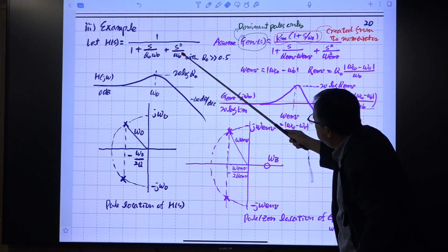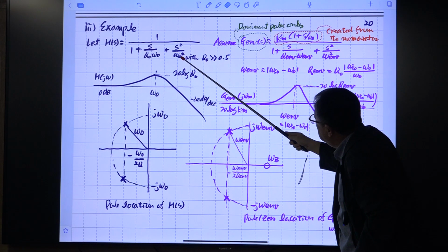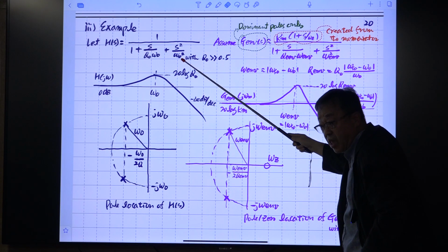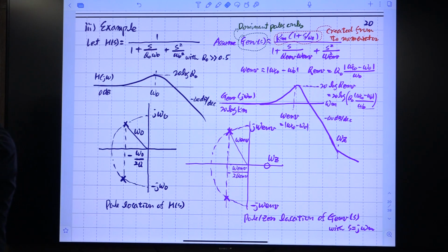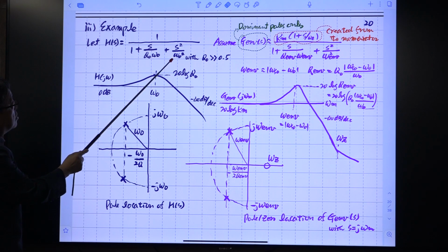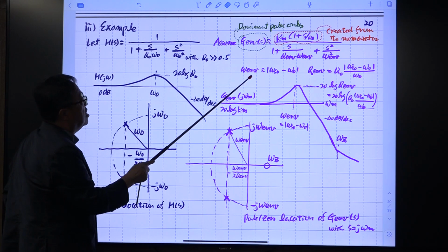From here, we know this omega naught, the resonant frequency of the tank circuit, and we know the switching frequency, the unmodulated switching frequency. That is the carrier frequency. You select the steady state switching frequency to place the region for ZVS or a good light load efficiency, whatever. So this is known, and this frequency is also known.